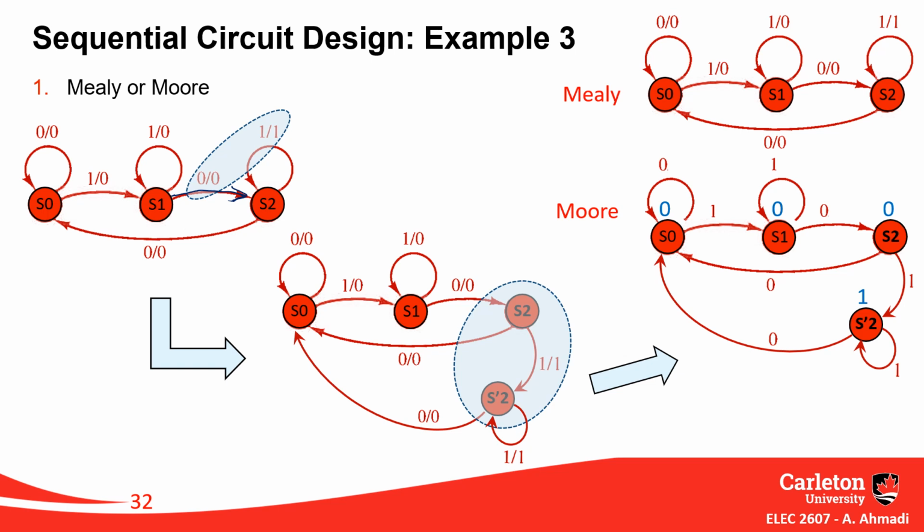Moore machines give you a better, more stable design compared with Mealy machines. Sometimes you definitely want a Moore machine, never going for a Mealy machine, because of timing hazards and difficulty which might happen in transitions between different values between clocks.